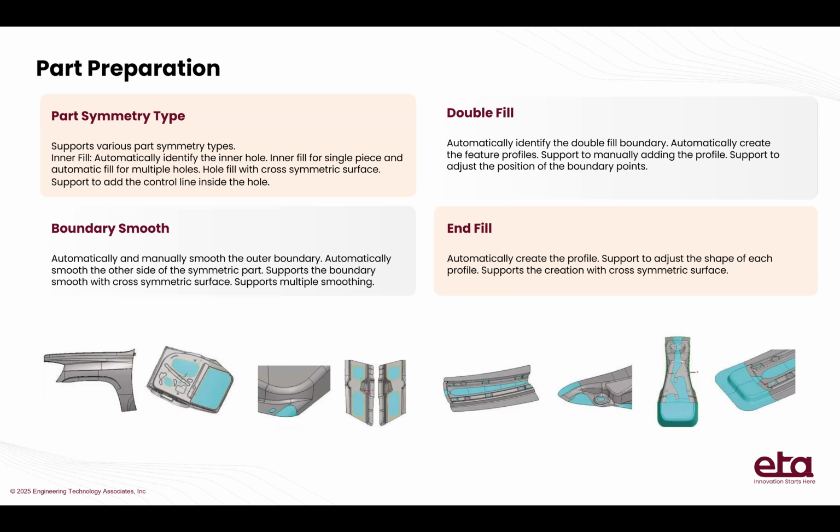We will now go through some key features in the DFD to see what it supports and how we make the die face creation easier. So in part preparation, after the user imports the product design into the database, the user can do many quick edits. First, we support many types of parts. You can see a lot of the demo parts at the bottom. We support a single part, double attached for the same part, or for the mirror, or for the rotated parts. Also, the boundary smooth, double fill, and end fill can be easily done here.